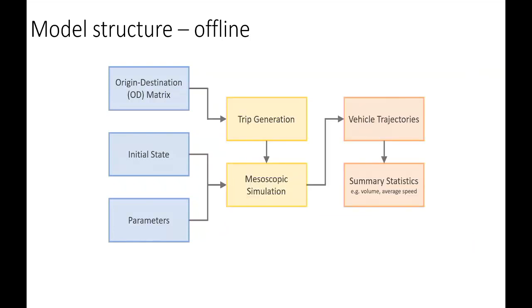Now all of this goes in here, and we generate a bunch of trips. Starting from the aggregate demand in the OD matrix, you generate trips which follow certain routes through the network, and the driver then wants to follow that. These are generated randomly throughout the simulation period.